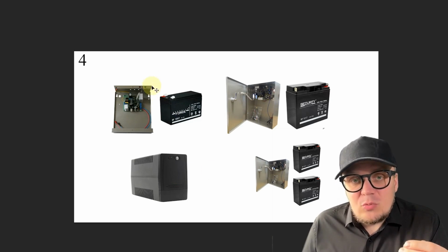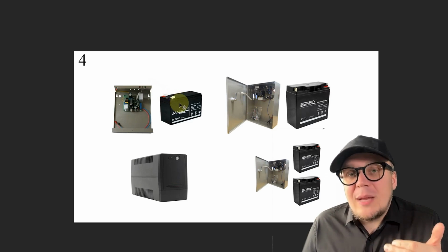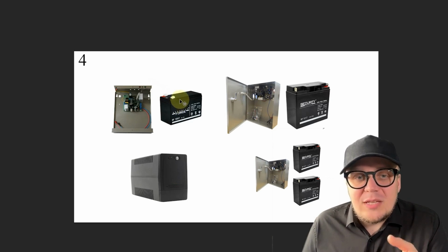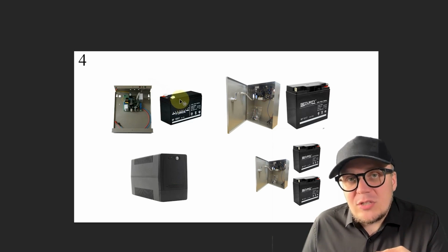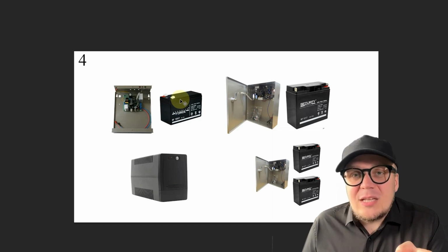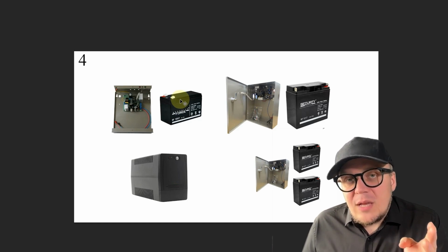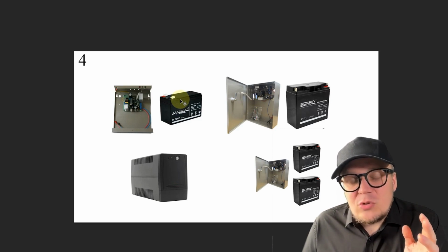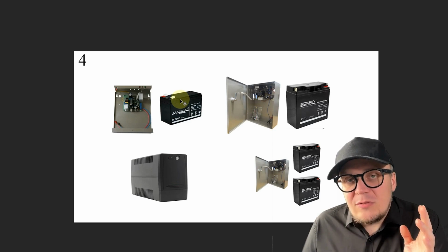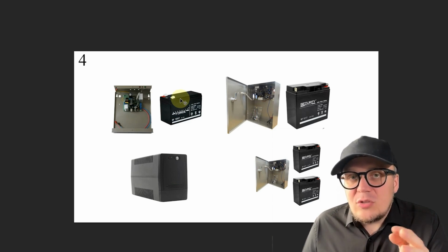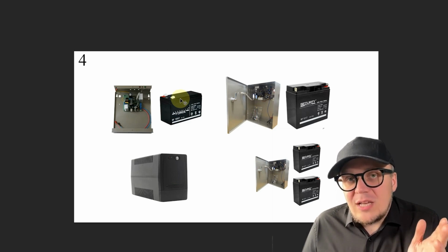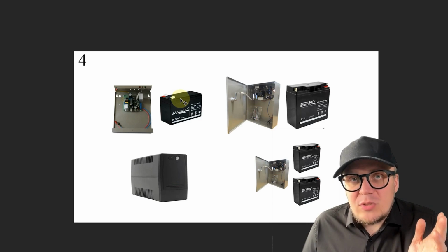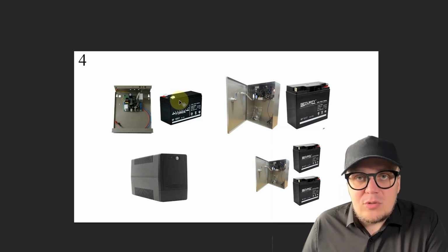Basically, of course, these are always sources that have a battery. That is, the batteries ensure the operation of your surveillance system in the event of a power outage additionally. And a common mistake here is when a person takes and installs a regular computer uninterruptible power supply. And here it becomes a lottery. There are a huge number of types, many of them are budget friendly, and whether it will help or not is already a matter of chance. No one can ever guarantee you that your surveillance system won't get damaged with such an uninterruptible power supply.